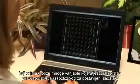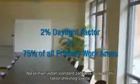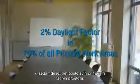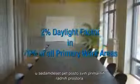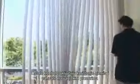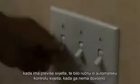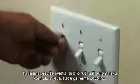Regulating the amount of illuminance critically depends on a good design that considers the many variables affecting the amount of natural light available for a given task, and then meets the objective of using natural light in a significant amount of the space. For example, one standard requires a 2% daylight factor in 75% of all primary work areas. Other controls include the use of shades and external window treatments when there is too much light, and either manual or automatic electric light controls when there's not enough.